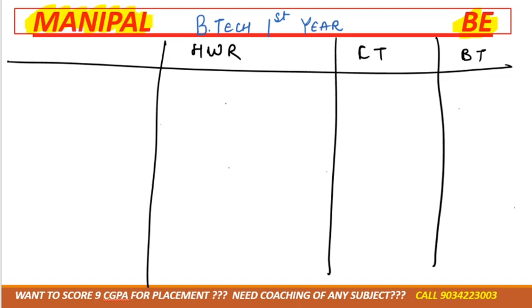So there is a fixed value basically for ripple factor. For half wave rectifier it is 1.21, and for full wave rectifier it is 0.482.